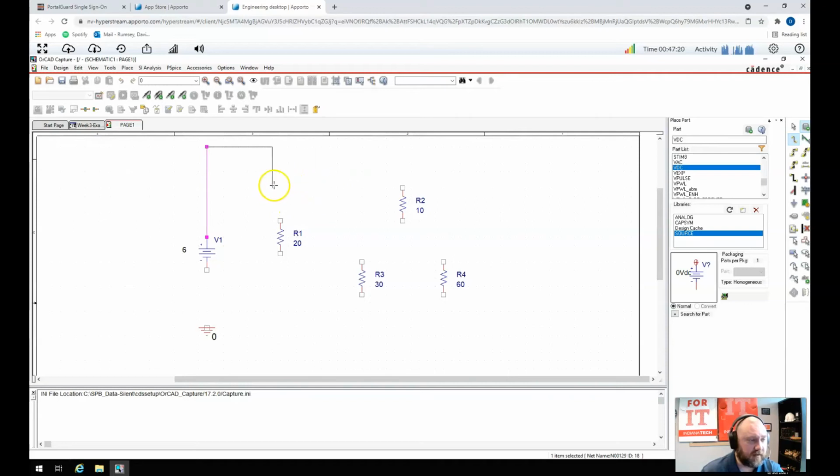And then now by left clicking, I've basically forced this wire, the purple wire now, to be that high. And I can kind of just go through, and now I can see, okay, if I want to connect it here, there's this red dot, and that's not showing an error. That's just saying if you connect here, you're going to connect the resistor and the battery up, which of course we want to connect them up. Now, the 10 ohm resistor is connected to the same wire.